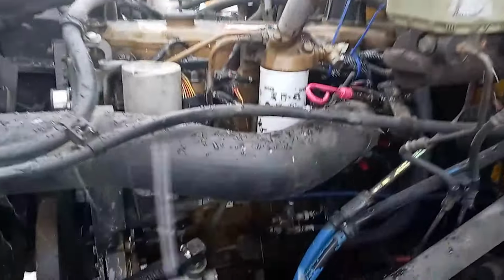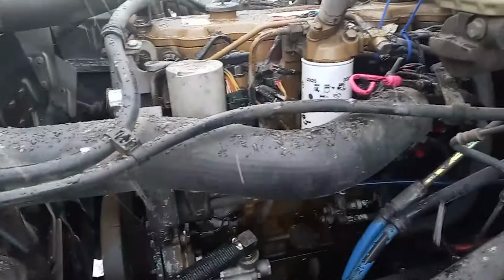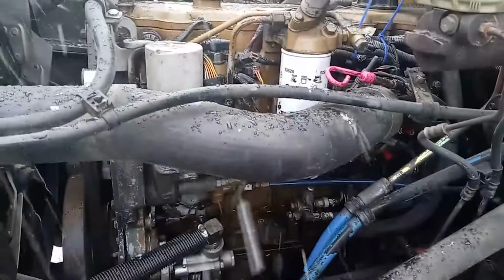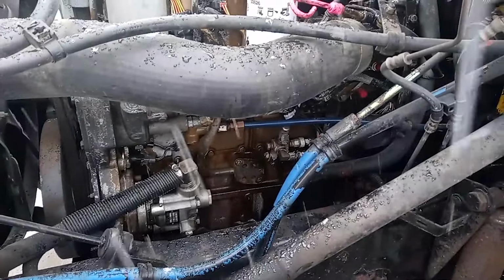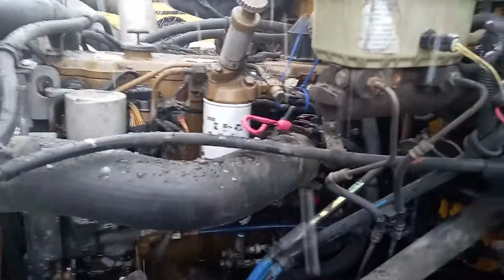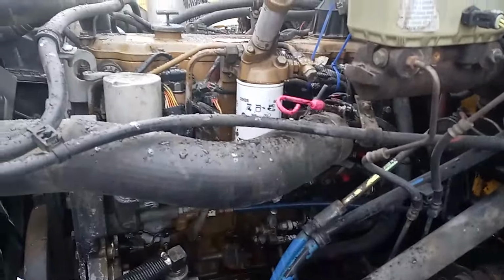Now how do I know it's maybe not a timing sensor problem or a fuel sensor problem? Well, there's no fuel sensor, but a fuel pressure problem. Well, it might have other problems, but with it not building HEUI pressure, that needs to be addressed first. The timing sensors have nothing to do with it building HEUI pressure, neither does the fuel system. So we need to figure out that why.